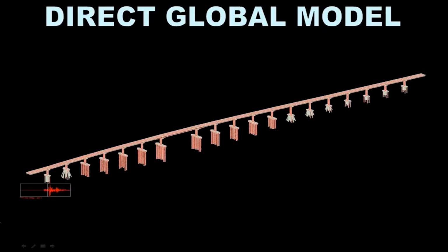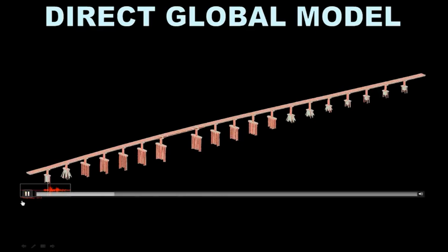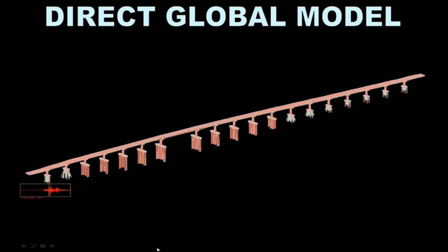So here is a direct model using Midas. All the nonlinear springs are attached, and you can see all the actions actually are at the main channel, as was expected by looking at the schematic drawing of this profile. So this is a direct model, nonlinear springs, everything is attached, and we have outstanding comparison between the Midas and recorded motion, specifically in the transverse direction, which I will show you later. I don't have the slide here, but I'll grab it and show it to you.